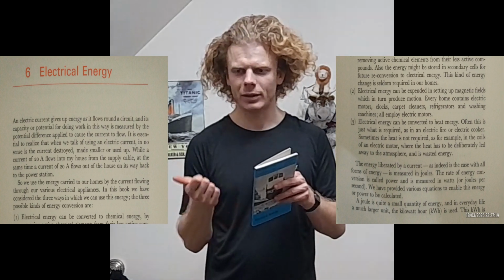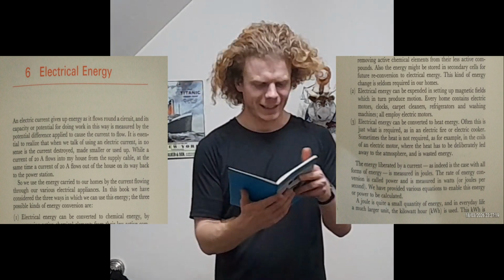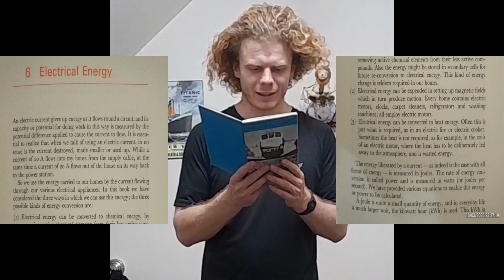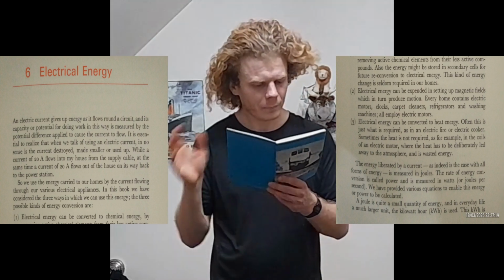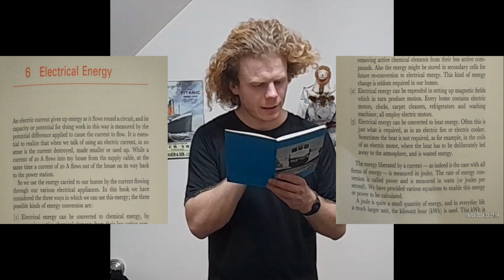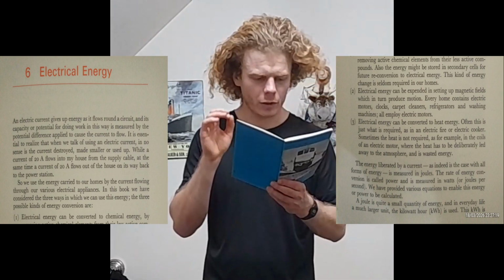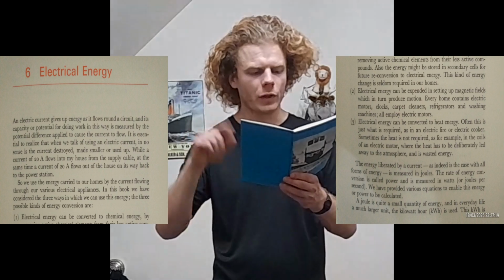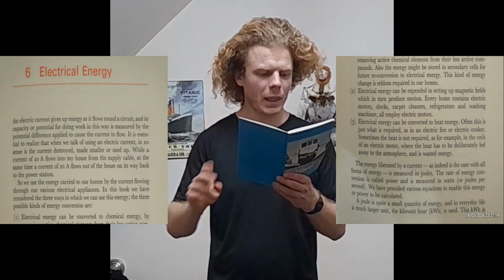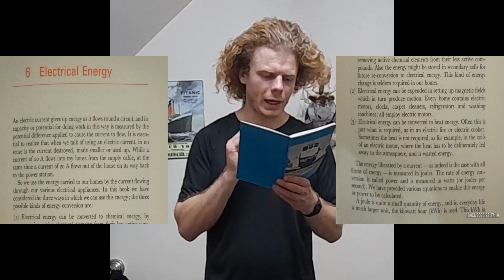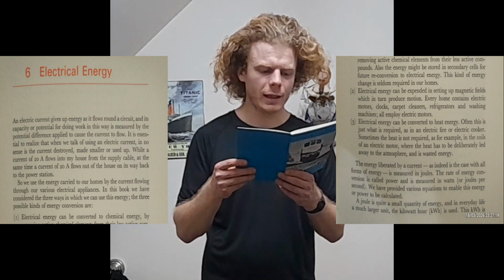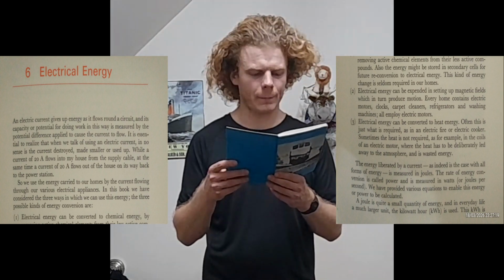What are they? Pounds? Pence? What could that be? 2 pence per unit. So 100 watts for 20 hours equals 2000 watt hours, and 2000 watt hours equals 2 kilowatt hours. And the cost of 2 kilowatt hours of energy is 2 times 2d, which is 4 pence.